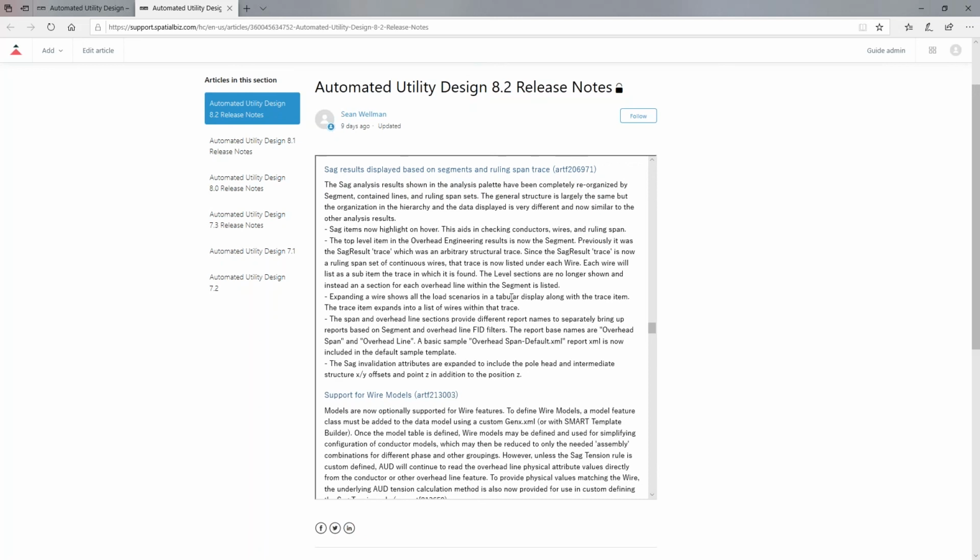A couple more questions have come in. Dave, this is a good one for you. How does the ability to configure layout in ducts affect pulling tension analysis, or does it? It really doesn't affect pulling tension. It's designed more to support data tracking. The impact on pulling tension would still be based on calculations of things like jam ratio and configured arrangements like that. So that physical arrangement doesn't directly impact it. It would be handled through the ways that you'd specify jam ratio and things like that previously.